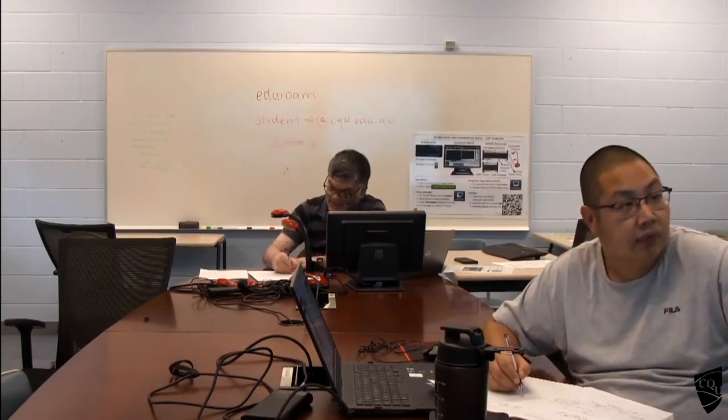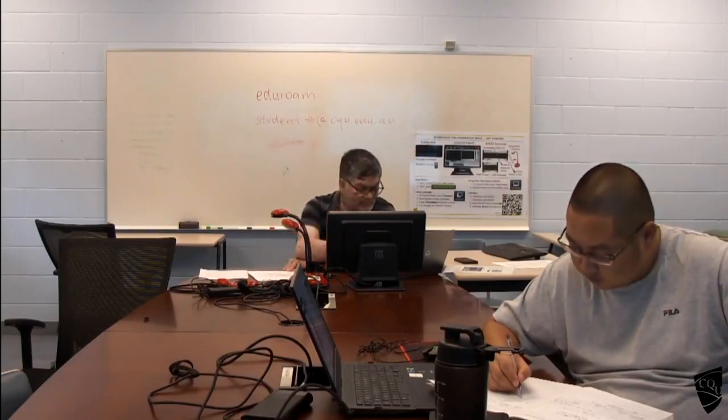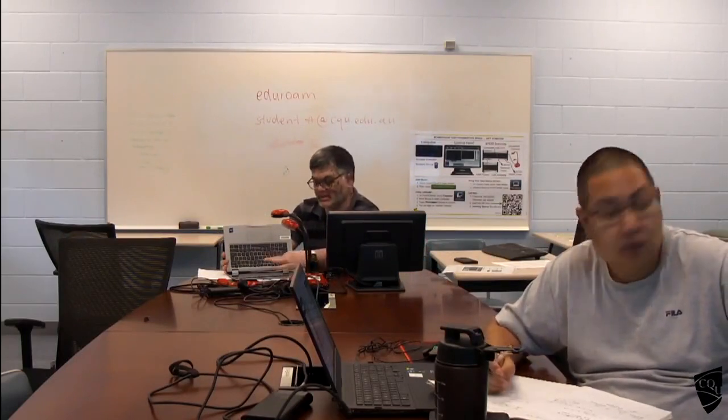Okay, so if you add, you will get the I value that is given here. This is the area of the rectangular section, this is the area of the equivalent steel.